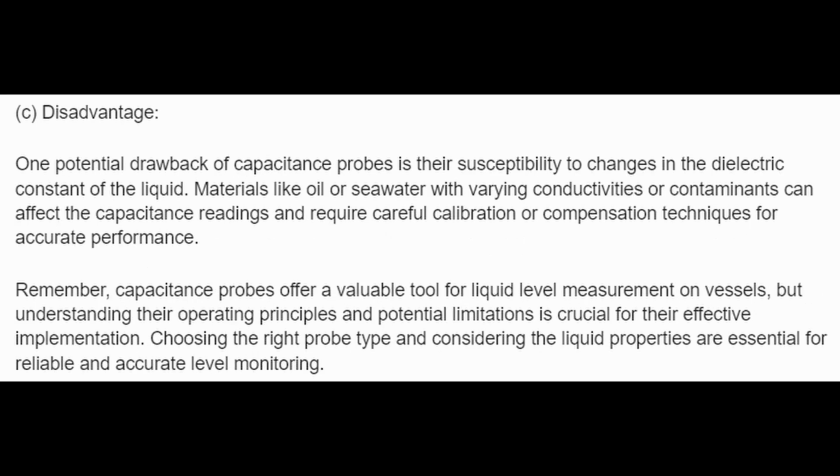Disadvantages. One potential drawback of capacitance probes is their susceptibility to changes in the dielectric constant of the liquid. Materials like oil or seawater with varying conductivities or contaminants can affect the capacitance readings and require careful calibration or compensation techniques for accurate performance.